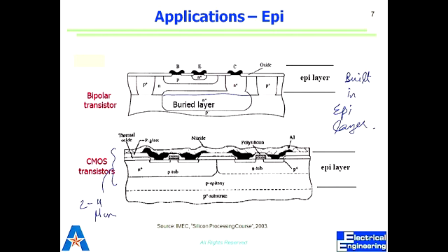If you take a look at that, there is a P-type substrate, and then this whole depth is made by epitaxy. So the whole bulk of the device is contained not in the substrate, but in the layer which is built on top of that, because now we have more control in making different concentrations of dopants in there.